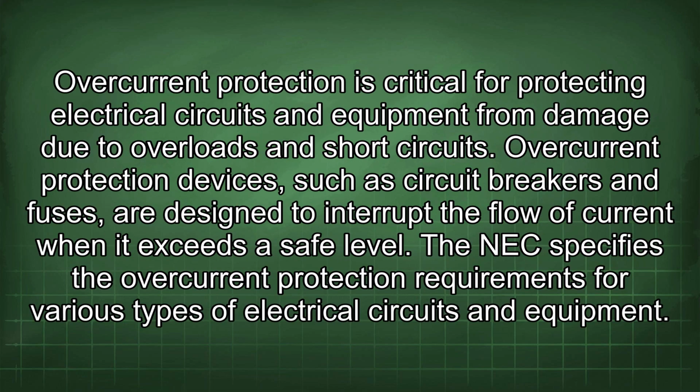Overcurrent protection is critical for protecting electrical circuits and equipment from damage due to overloads and short circuits. Overcurrent protection devices, such as circuit breakers and fuses, are designed to interrupt the flow of current when it exceeds a safe level. The NEC specifies the overcurrent protection requirements for various types of electrical circuits and equipment.